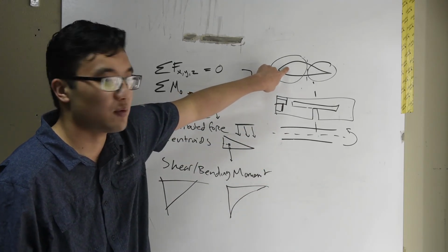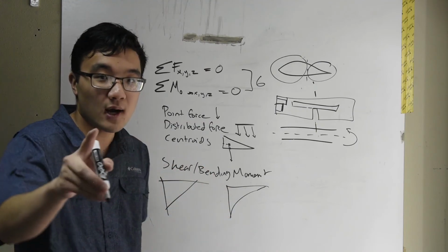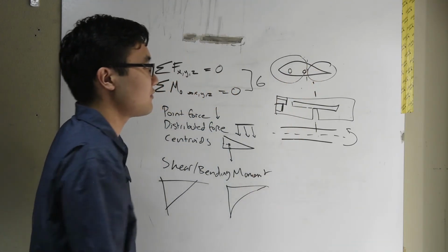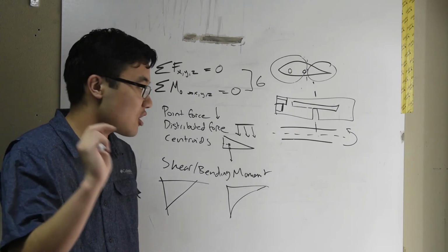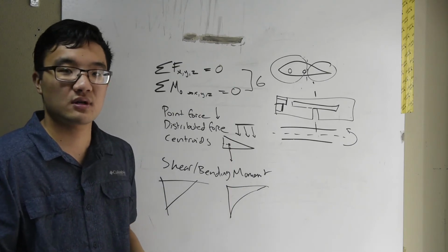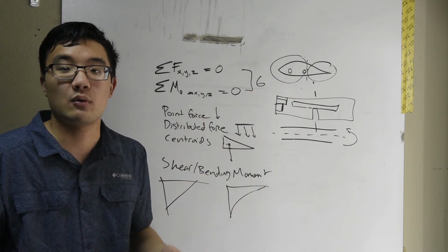I'm not going to cut this portion of the wing away. That's the strongest part of the wing. I need that. Which is why our carbon fiber rods in the wing went right through there to support that strongest area, that area that takes the most load. When we talk about the summer composites report, we're going to talk about how we know this takes the most load too, just by watching.